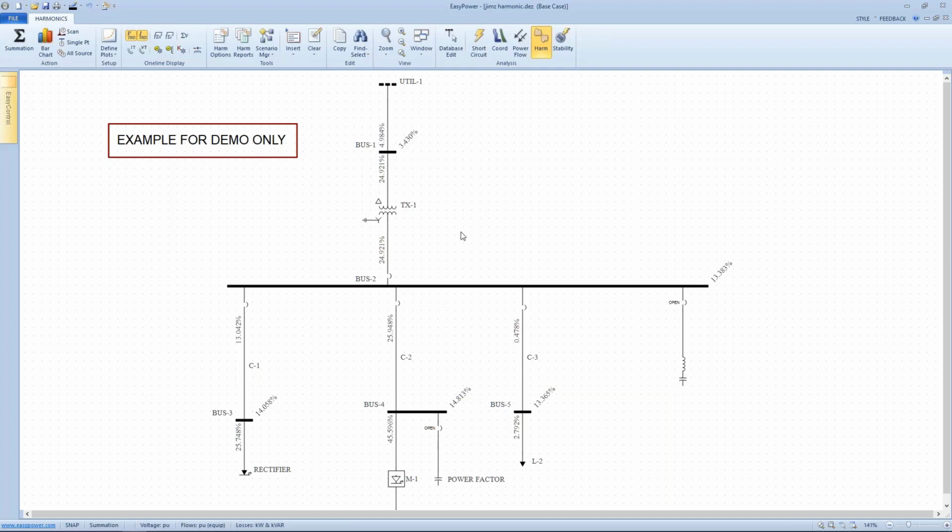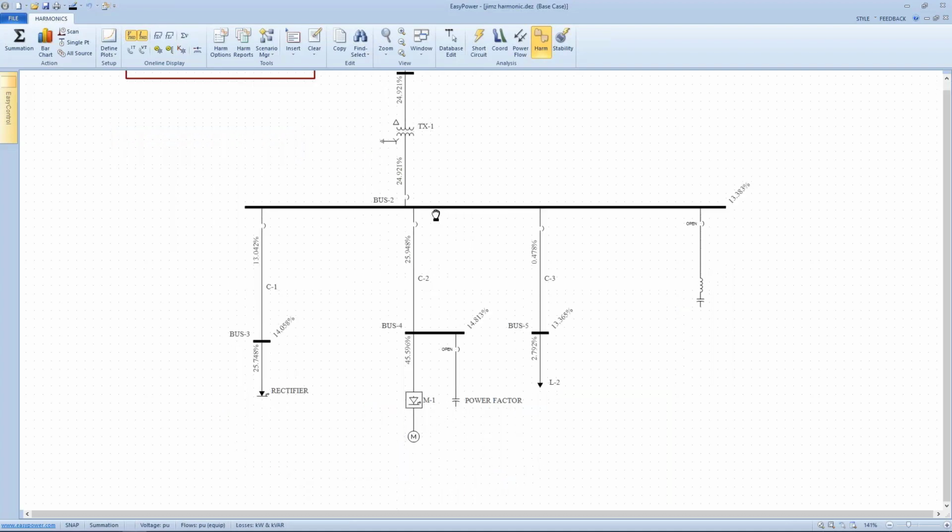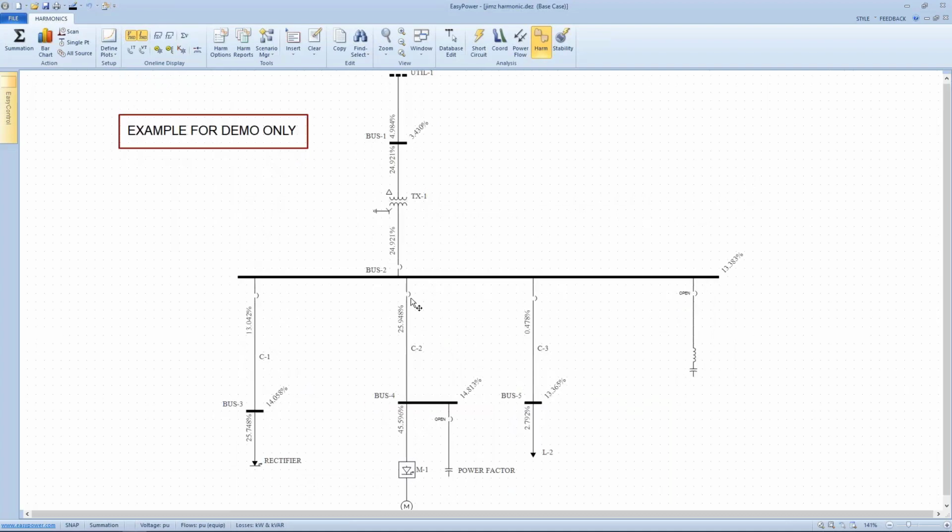So this brings up the question, what else is going on, or what other concerns should I have other than just removing the power factor correction bank? If we notice this top series of buttons, it shows the VTHD and ITHD, again for all the system.